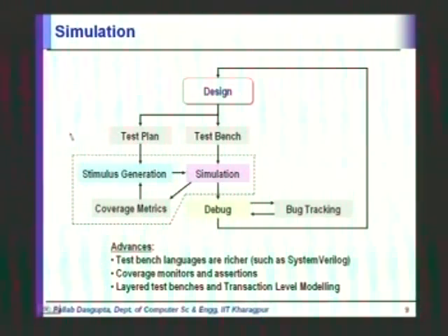So the test bench here is that wrapper. Its job is to take the tests, which are typically written in Verilog, and integrate them with the design so that when the two are simulated together, the tests are fed into the design. And similarly, the outputs from the design may be recorded or dumped. Now, alongside this test bench, we have a very important thing which is called the test plan.